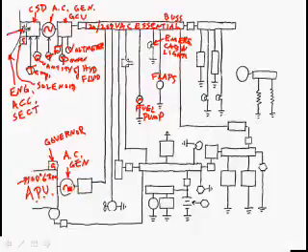just like the governor on a constant speed propeller, that keeps it at 100% all the time. And so that's going to be geared especially to run that AC generator right smack at that one particular RPM, so it'll put out 400 hertz. So you don't need the constant speed drive with a governor in it, because we have a governor running the APU. But we're still going to need a generator control unit, and you can feed it into the essential bus if you want to. To start the APU, we're going to need an electric motor, and there's a contactor, and that's going to be connected to the low voltage DC, or 28 volts DC bus, and that can be powered through a contactor by the battery.